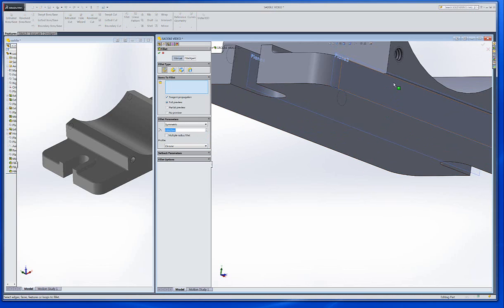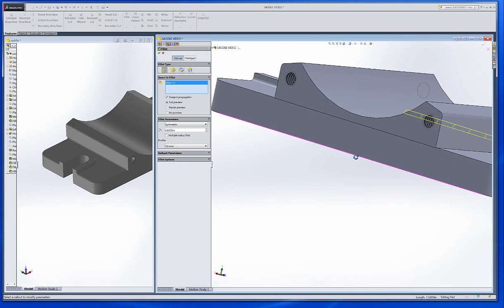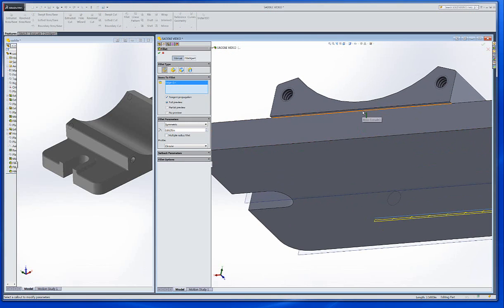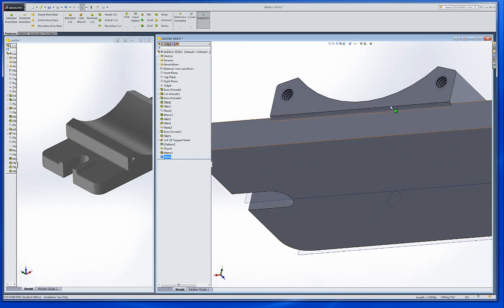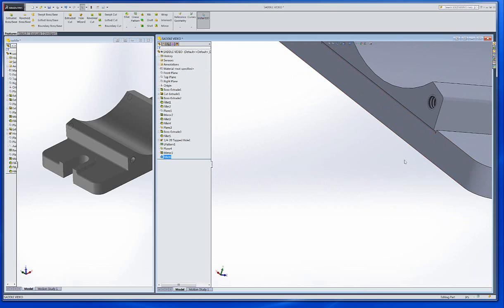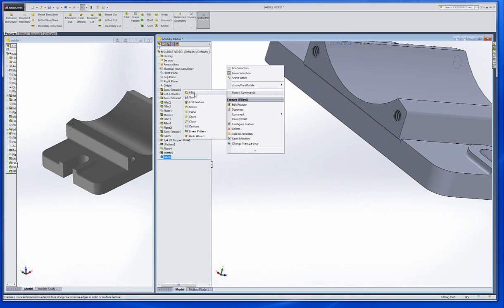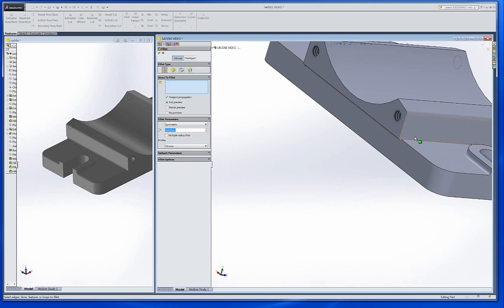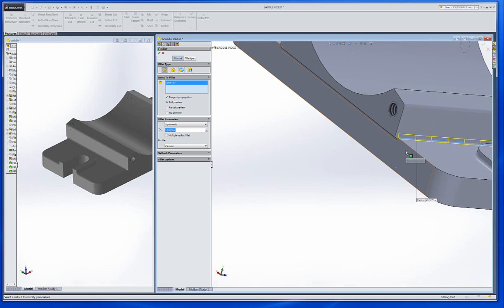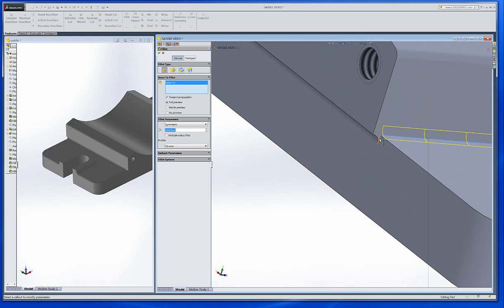And we'll go in there and pick this line right here, and we'll rotate around and pick the same line on the other side. And a lot of times you're better off if you do these separate from other stuff. It might be easier. Okay, we'll do another one. We'll just go recent commands, fillet, still in 1/16 of an inch, so we'll hit this line right here. Now note that's just getting that one, so you might want to go in there and grab that line.